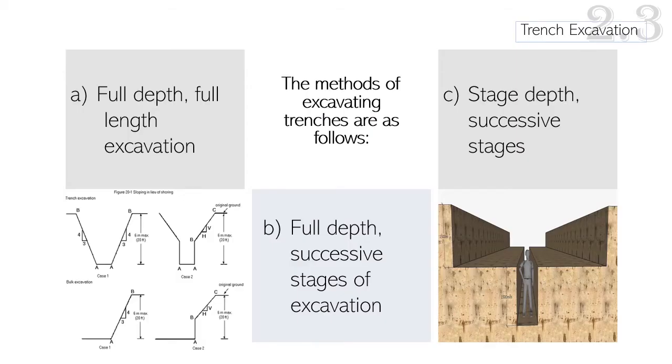There are three methods of trench excavation: full depth, full length excavation; full depth, successive stages of excavation; and last but not least, stage depth, successive stages.